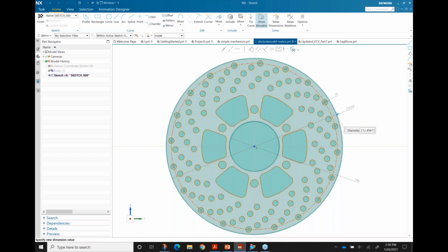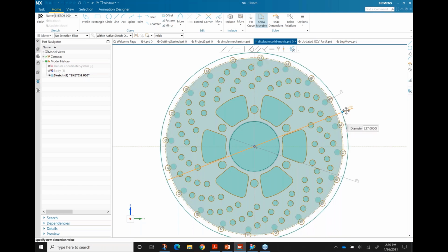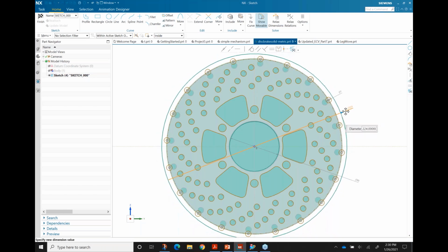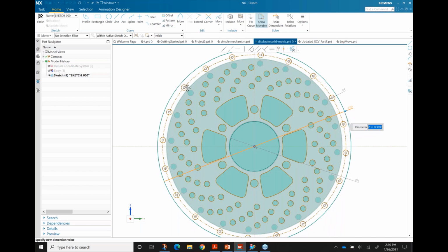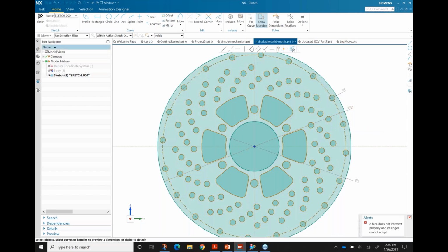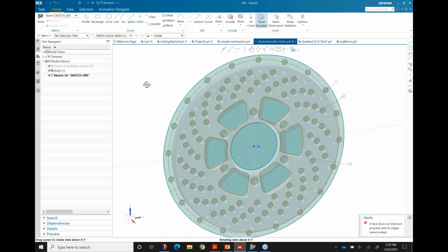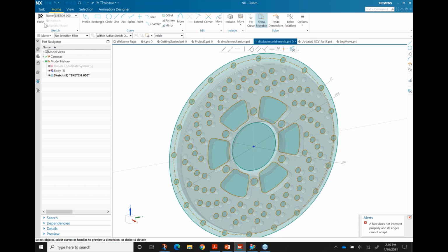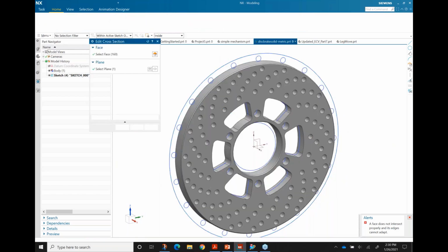But now if I were to go in and make any adjustments, you notice how the software identified, wait a minute, a reference circle went perfectly through each one of those centers. So it added another relation, an offset. So very, very fast. I'm just going to bring back the body and I'll finish my sketch and watch what happens.